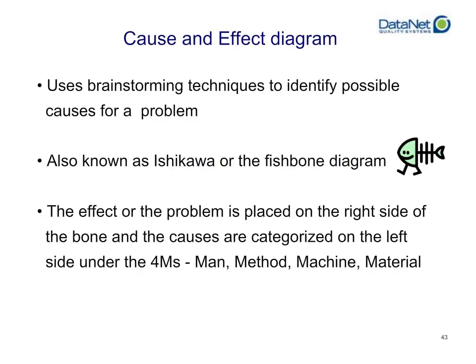So the next SPC tool that we're going to be talking about is going to be the cause and effect diagram. So cause and effect diagrams allow you to start analyzing your problem. It's still in the problem identification because you're not necessarily knowing what the problem actually is yet, but at least it's going to start sending you hopefully in the right direction. Cause and effect diagram primarily uses brainstorming techniques to identify possible causes for a problem, also known as an Ishikawa diagram or a fishbone diagram.